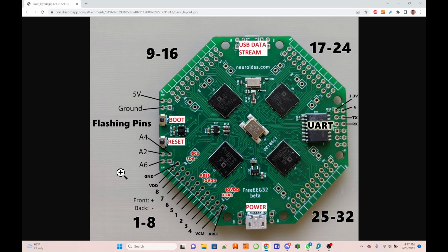Here we have the option whether we want to connect all those negative terminals of all the channels together or not. If you do it, you have to do it physically with a wire. The OpenBCI board has the option of doing that from a single pin out, which is already on the board, and that pin is called SRB2. So SRB2 is a collection of all of the negative terminals of the 8 channels on the Cyton board. Here we don't have that, but you can make it yourself by connecting all of the negative terminals, or you can take a number of negative terminals, connect them, and keep some channels available for different montages.